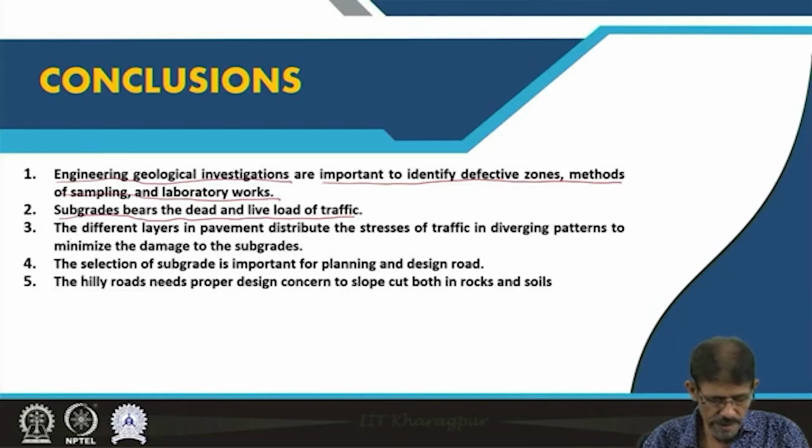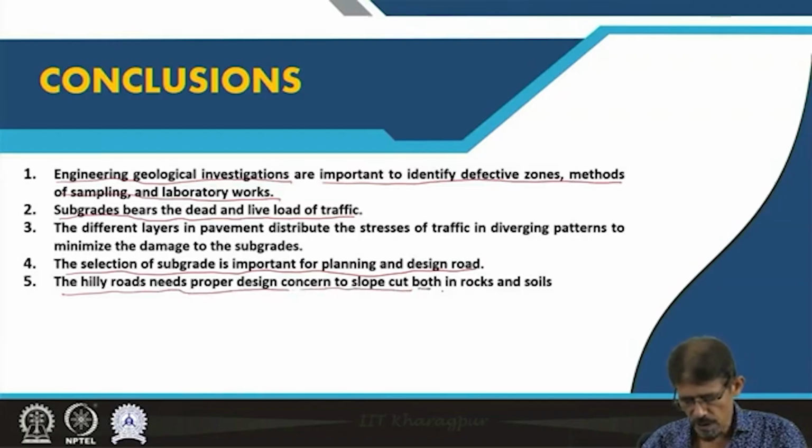And the selection of subgrade is important for planning and design of the road construction, and the hilly roads need proper design concerned with slope cuts both in rocks and soil, along with consideration of nature of vegetation, density of vegetation, thickness of soil cover, availability of drainage, etc.